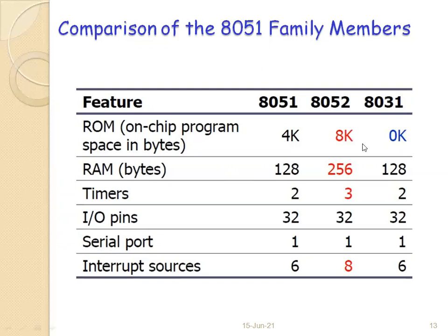Starting with the 8031, you can see that it has no ROM specified, because it has no ROM. It is basically a ROM-less 8051, so it is 0 kilobytes. The option is given to the user to choose a particular ROM size, which will be connected with the 8031 to make it functional.